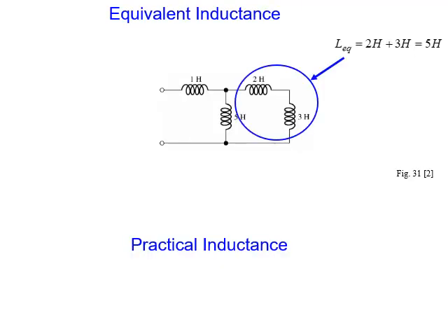Now see, when we have more than one inductance connected together, how do we find the equivalent? We start from the last, or the farthest point from the source. I mean, here is my source. Then these are the last, or farthest, inductances from my source. They are connected in series, so 2 plus 3 equals 5.